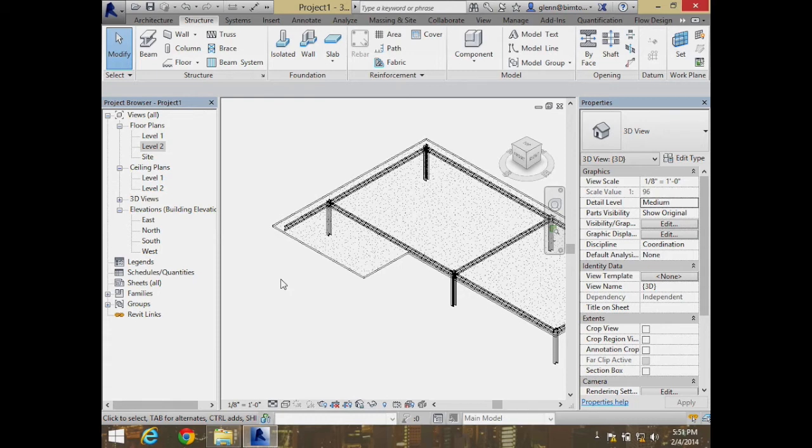In terms of supporting this piece out here, what I'd really like to do is tie back in somewhere further into the structure. Now I could tie all the way back. I could tie part of the way back. If this were not steel, if it was wood, we'd be using a rule that says if you cantilever about 1/3 the distance of the total length that's supported back on the other side. So kind of a 1/3 to the other side. Steel actually has a lot more support to it in terms of being able to support cantilevered loads. It's really more durable in terms of what's going on.